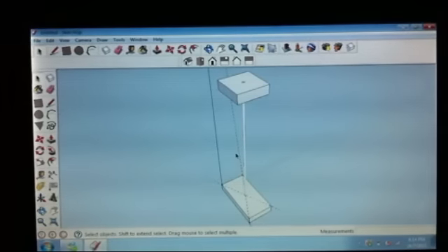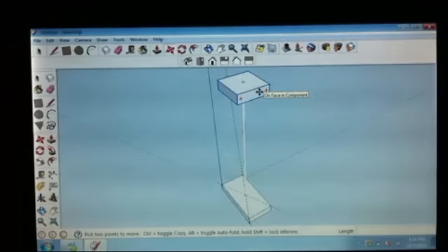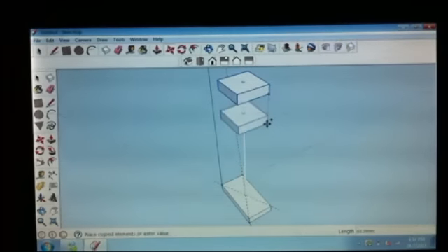Okay, so how are you going to do that? Similarly again, you can copy this to bring this thing down. Alright, let's recap. How do you do that? You go to the move button. You click on it, you let the cursor go into this. You must press the control key. Can you see there's a plus coming up again? And then we are going to move this thing down by, say, anything, maybe 40 mm. Alright, I enter.